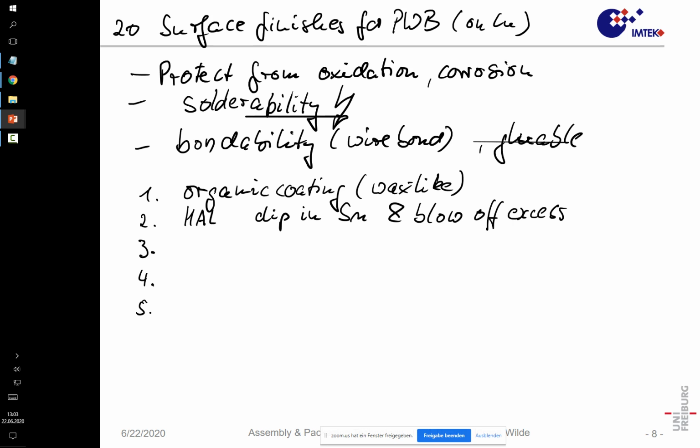No. The disadvantage is in electroplating you must connect all metallic surfaces with a cathode, yes? And that you cannot do because all metal strips and so are individual, yes? You would have to connect them, then you can electroplate, and then you remove this central connection. That's not a good thing. We use chemistry. We use chemical metallization.